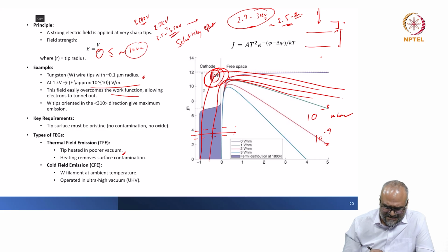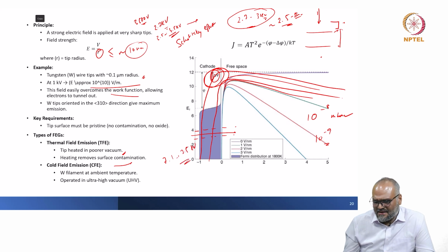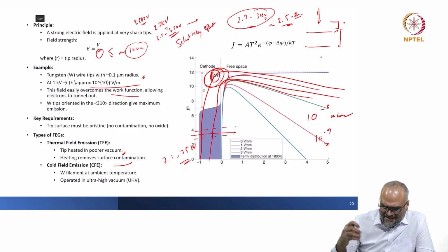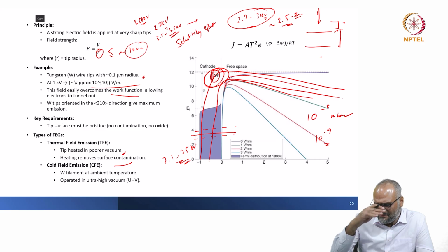But the challenge here is that the operating voltages in a field emitter go slightly higher. You would go up to 7.1 or 7.5 kilovolts even, and you would have the same two-anode construction here as well. Once you extract the electrons, you are also suppressing them by using the other anode, and you control the beam currents in a much more controlled fashion with a feedback loop.